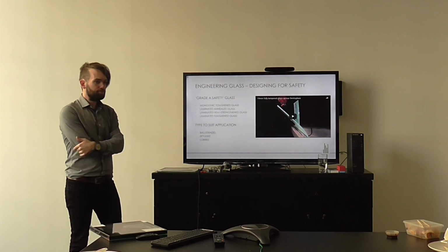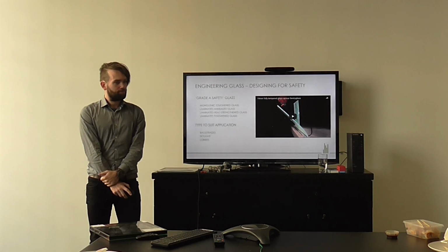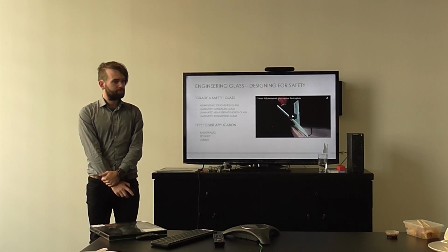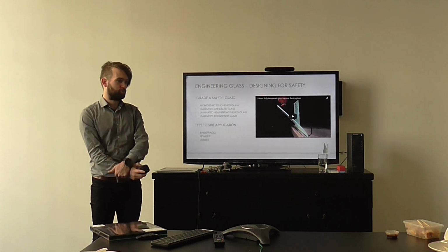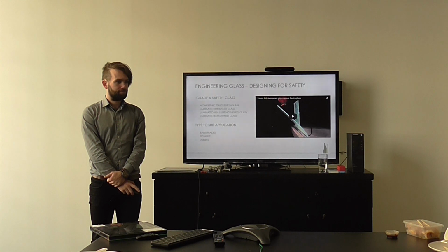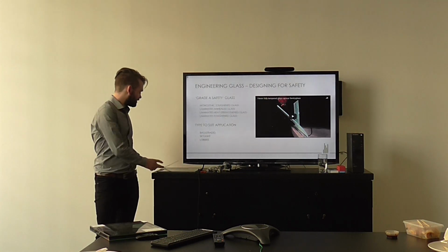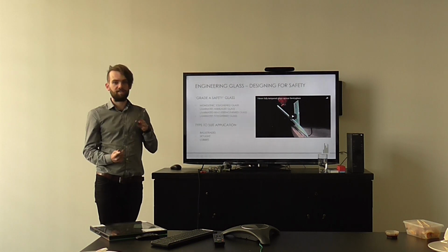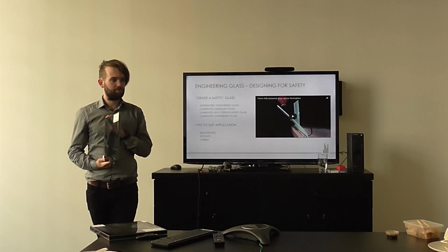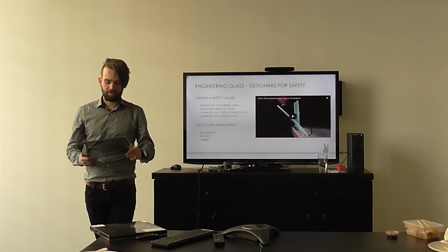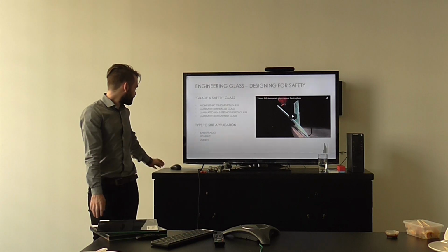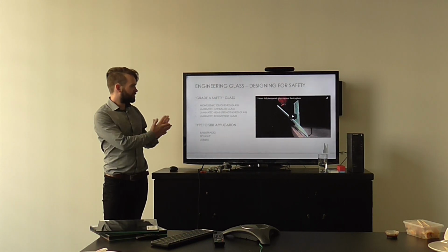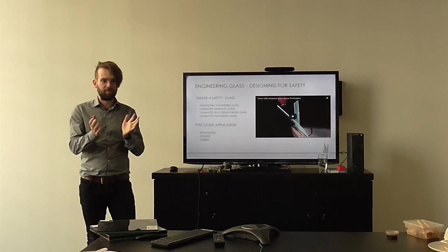Yeah, and I suppose if you're considering a laminated piece of glass to act together, you've got to make sure the dead load is transferred down through both. Because if you're only supporting one side of the laminate, then you're not really allowing it to act together. Yeah, absolutely. You'll be putting the interlayer into shear, and again over time it can deteriorate. We consider that we design our buildings for 25 to 50 years, so it's a decent amount of time for that to happen.